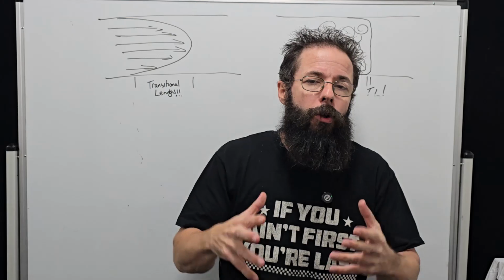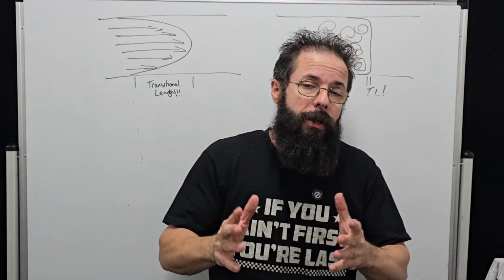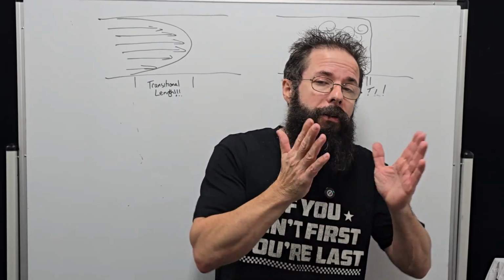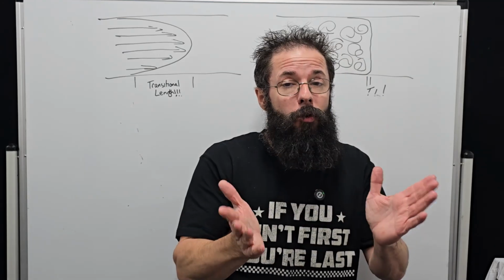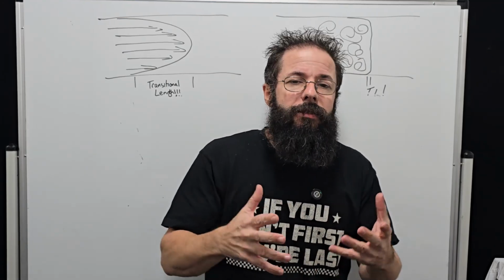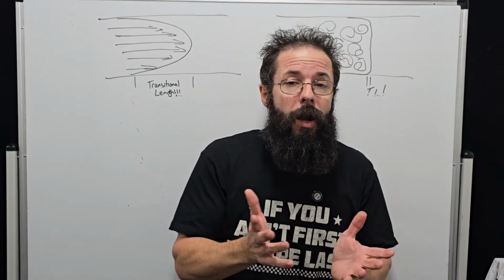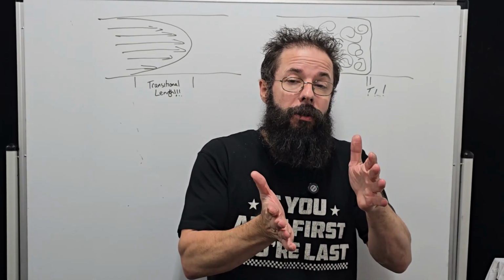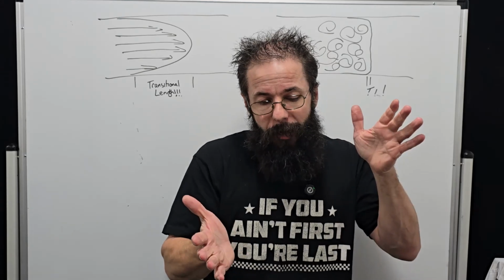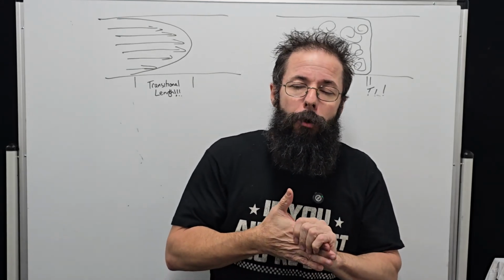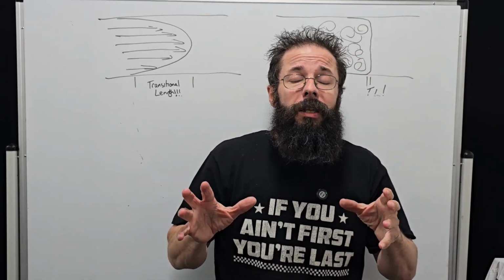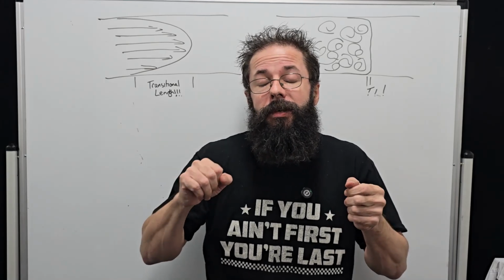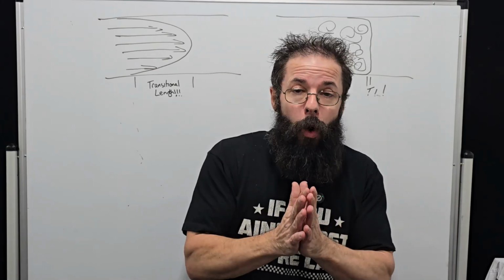And it's not that the port turned turbulent, it's that the turbulence got out of control or we've seen separation. And that's always a problem, because separation and too much turbulence will create that dynamic CSA that I talked about. It'll shrink the port.